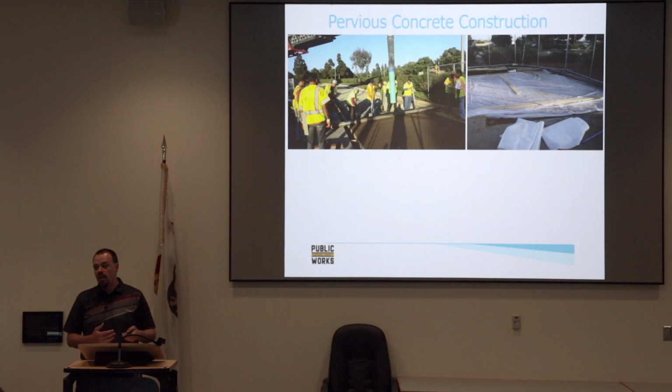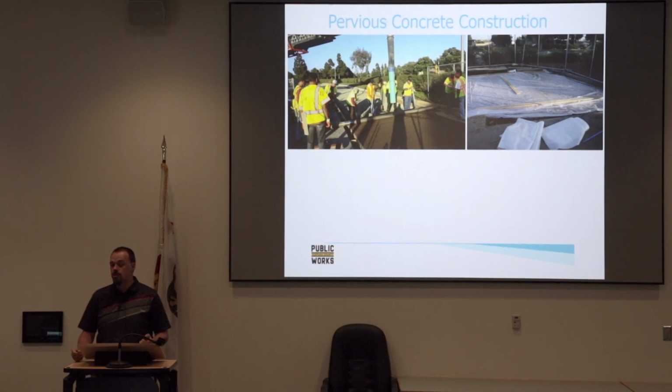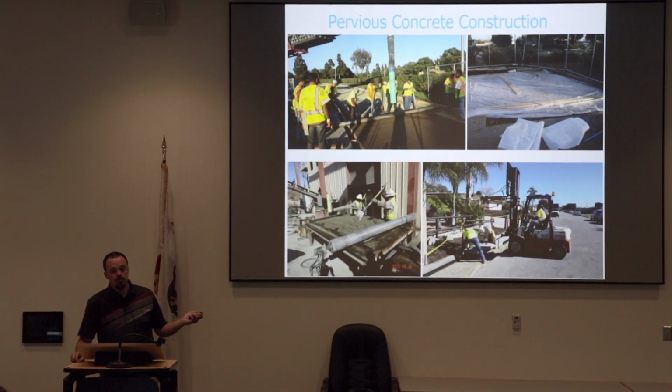So at the government center, where we have it in every single parking lot, that became a huge issue. Trying to coordinate with our ground services and closing off parking lots to make sure people aren't driving on it did become a big headache. So in retrospect, it might have been better to go ahead and do precast pervious concrete.